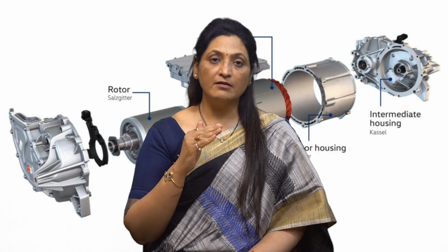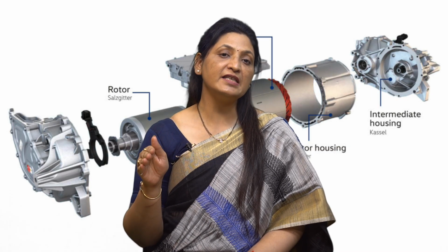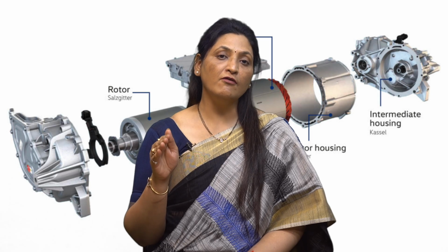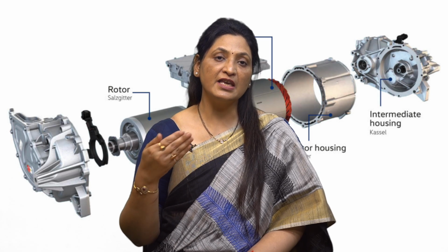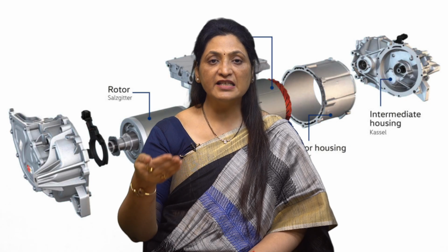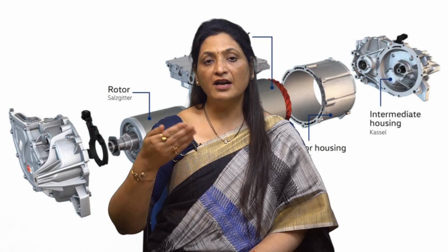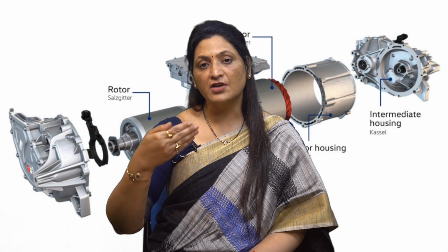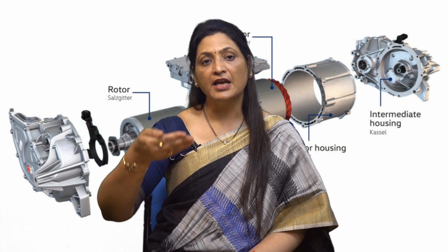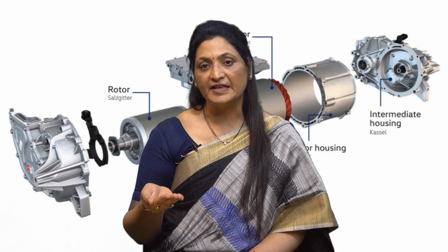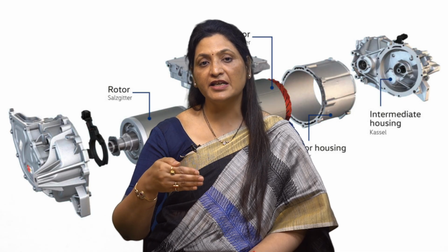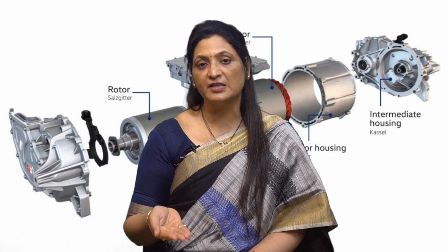So, it is definitely influencing the selection of motor power rating as the loading conditions keep on changing. So, let us see the heating under load. When a motor runs under load, it transforms some electrical energy into mechanical energy and the rest is usually released as heat. The motor's efficiency dictates how much energy is lost as heat.